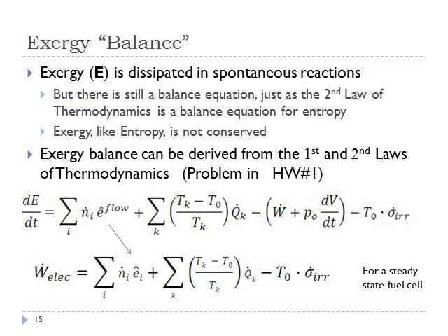And then we've got a term for thermal energy entering or exiting the system at temperature T sub k. And then we've got terms for work, so you subtract the amount of work. And there's a term you have to subtract off if the control volume's volume is changing with time. Luckily, we're not going to be looking at those types of systems. In our fuel cell systems, the volume of a fuel cell doesn't change with time, which is nice.